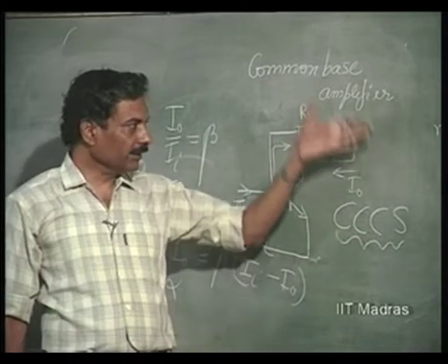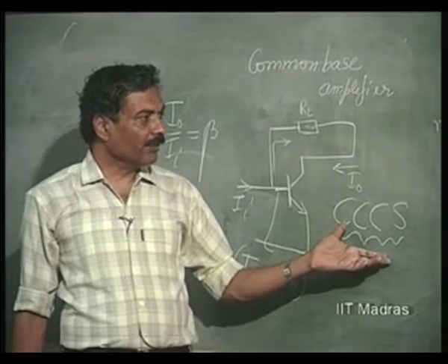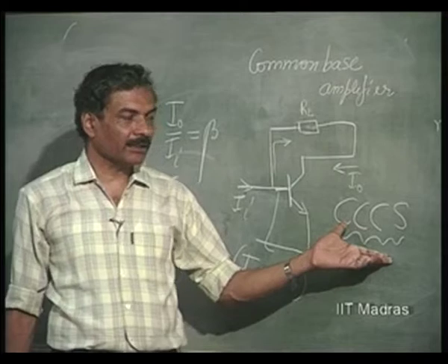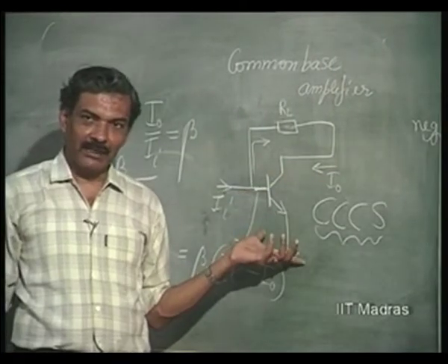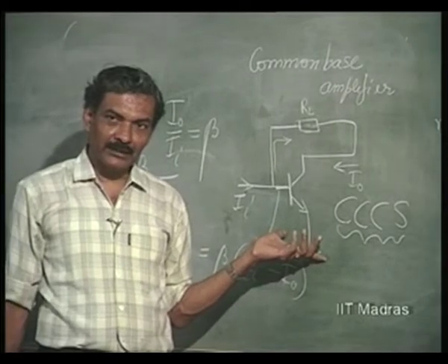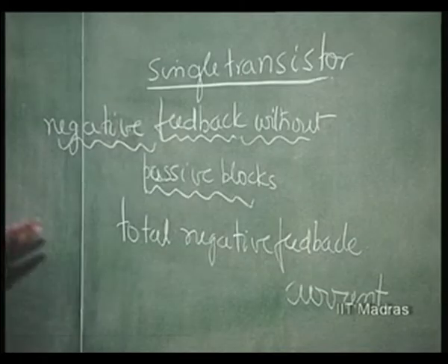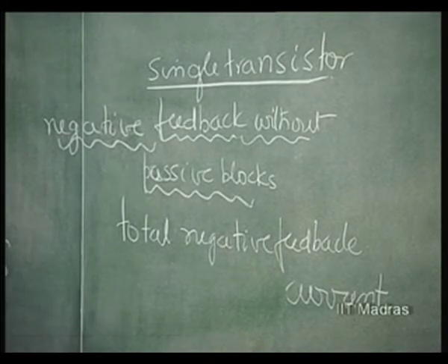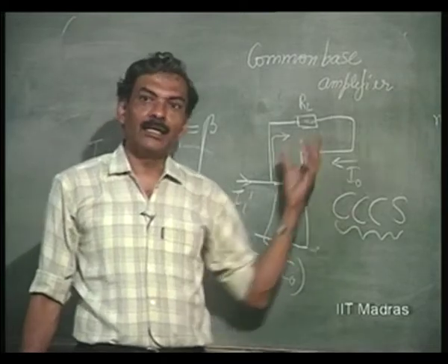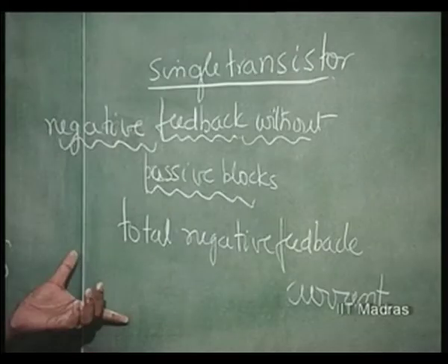Okay. So, these are therefore also called wideband structures. The common collector and common base structures will have a bandwidth which is going to be again loop gain times higher than the common emitter amplifier bandwidth, respectively for voltage gain in the case of common collector, current gain for common base.